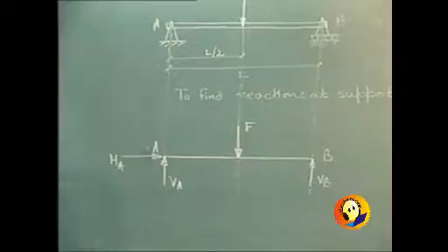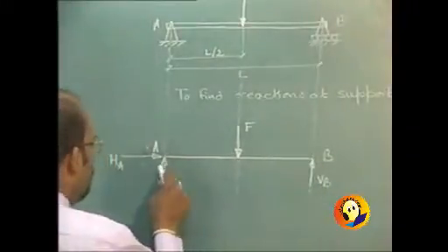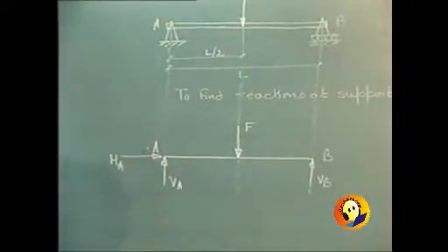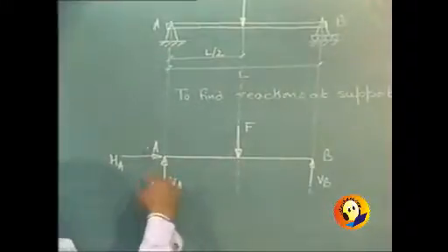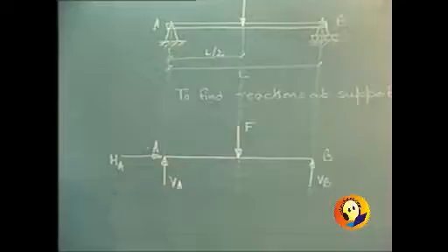The question is, why I have taken these forces upward and why HA towards right? Of course, there is no answer to this problem. You can actually take these directions in whatever manner you want, and the final answer will correct the direction if you have made some mistake into it.